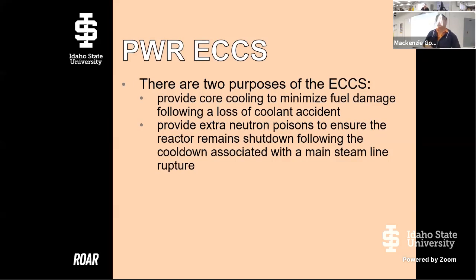A loss of coolant accident, or a LOCA, is something we'll learn about in detail in your last semester in our reactor steam supply systems class, or Thermo 2 class, essentially. But essentially, you can have large break or small break LOCAs, which are either a leak that is removing water so that you're having trouble keeping the top of the core covered, or a large break LOCA that essentially somewhere in your primary coolant system, you're losing significant water to the point where you're not able to make it up. You're not able to put water back in at the rate you're losing it, okay?